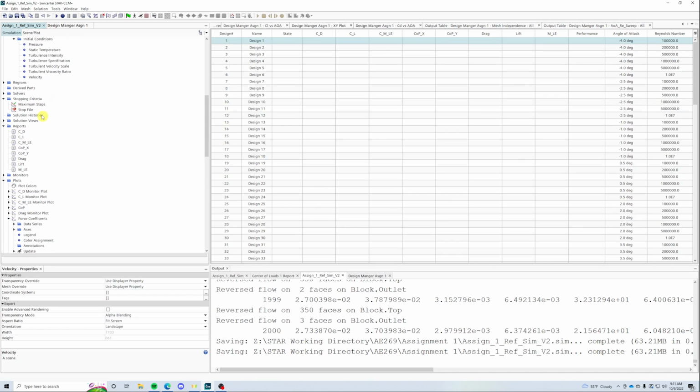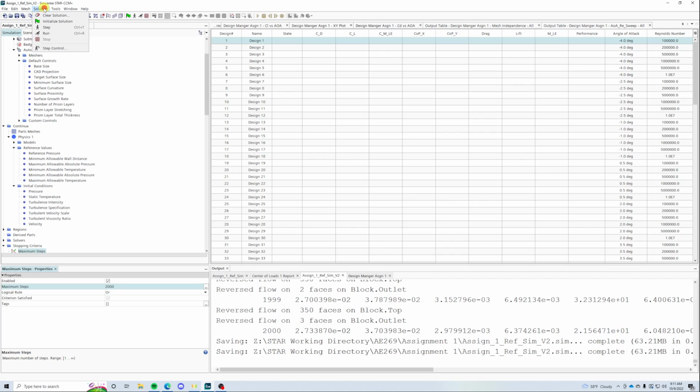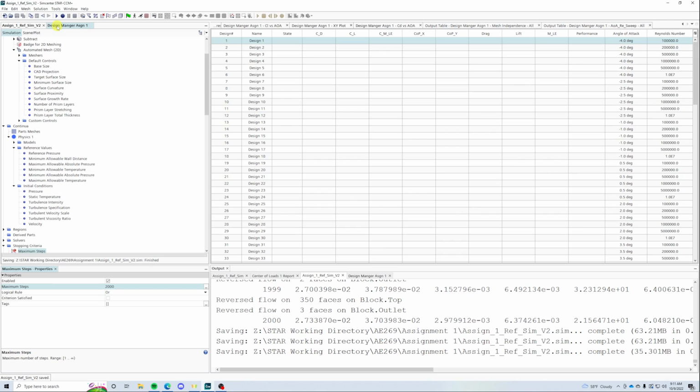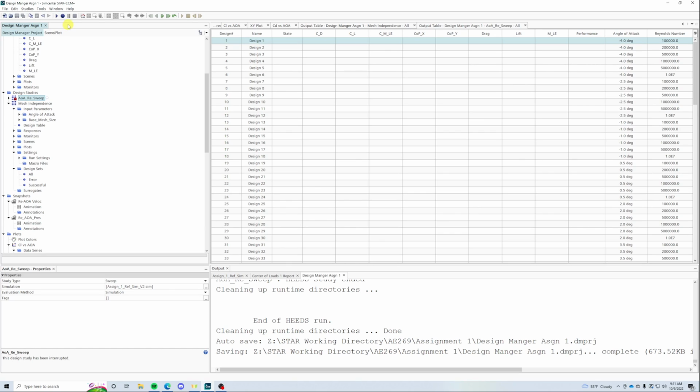You know what? We're changing enough things here that I'm going to just save that, because initial conditions aren't really going to help with such a wide range of velocities and angles of attack. They might be appropriate to help some of the simulations, but they're probably just going to hurt others.